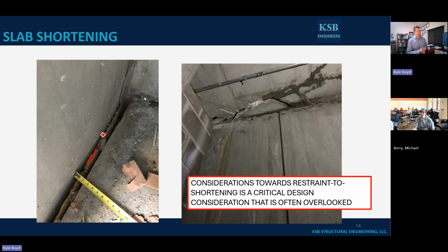That's expansion joint material. Whenever you're pouring concrete up against a concrete vertical surface, if you're not actually hard tying into it, you put some expansion board right there. That's about 1/2 inch thick expansion material. You can see that this is a 2-inch wide crack based on the tape measure right there. And really, if that was 1/2 inch board, that means that crack's opened up 1.5 inches. That's a lot of horizontal movement to be seeing with a concrete slab. And so that movement's very real. It's going to happen on your project, and you need to detail for it.